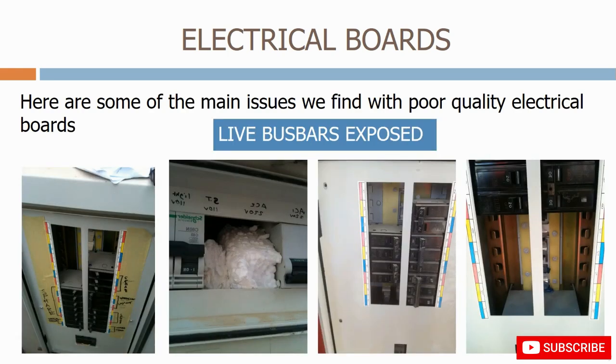The live busbars and terminals are exposed because blanking plates have not been provided. This puts anyone opening the board in danger.